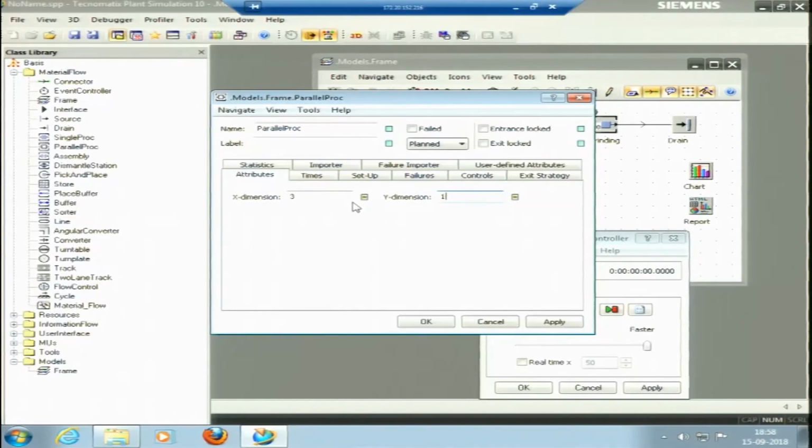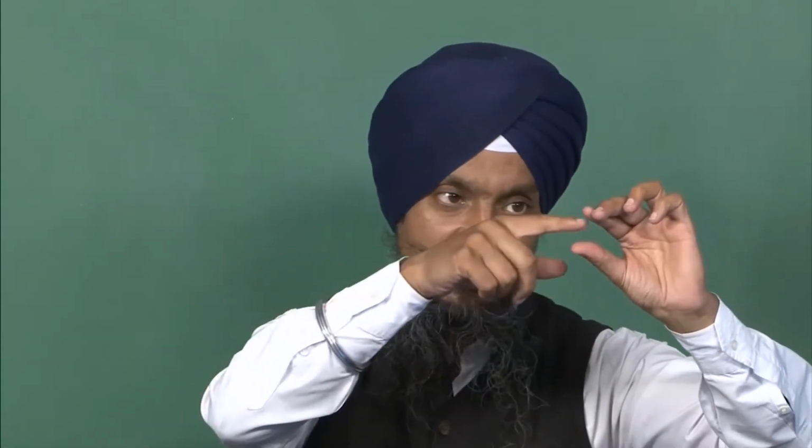And if there is a lot of waiting time, sometimes we can even think of doing some other processes, like I have said in the case of the process layout. In a process layout, we have a specific set of machines in one section, another set of machines in another section. If we see the overall machine time, and in this specific section for 30% of the time there is a blockage or waiting, we can give them some other job. Okay, some other job could be given.